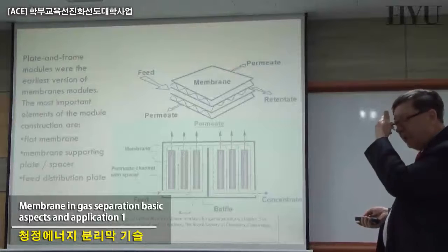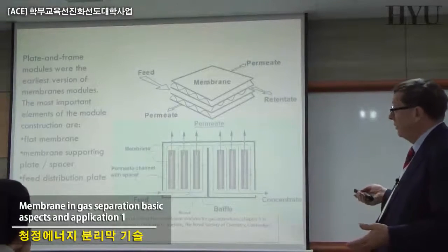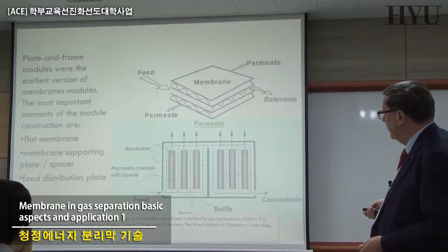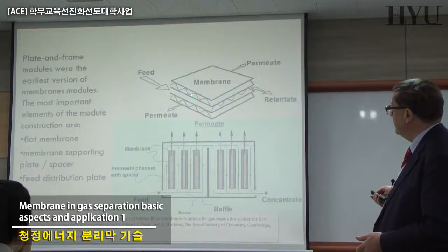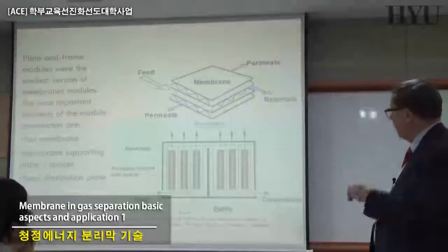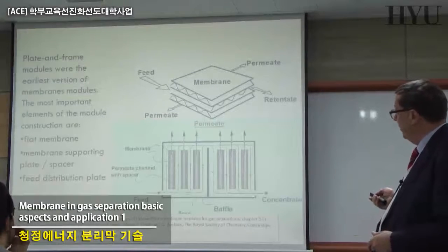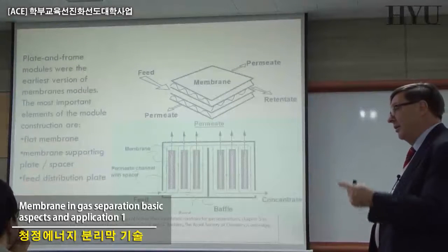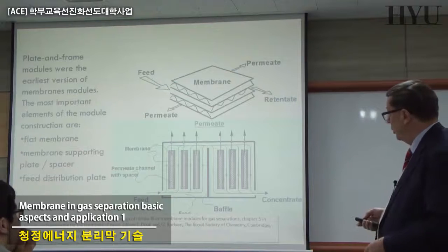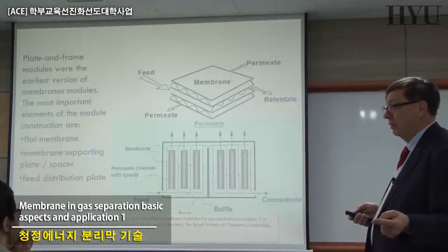Plate and frame has very few applications today, except small ones. It is the easy one, the initial one that everybody is doing in the lab. Also here you normally have spacers, and the control of the thickness and of the roughness, the geometry of the spacer, is very important to understand the interfacial phenomena, the concentration polarization, etc., that we learned already is as important as the quality of your membranes.